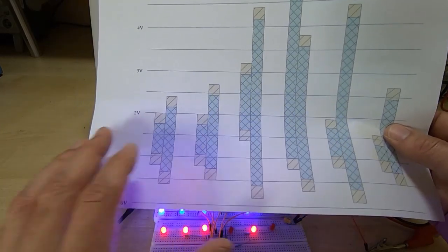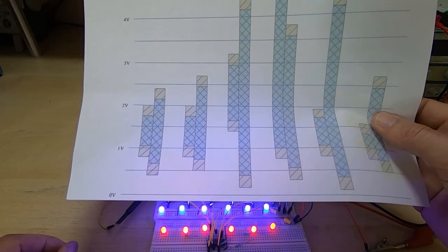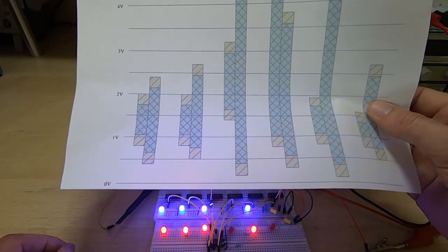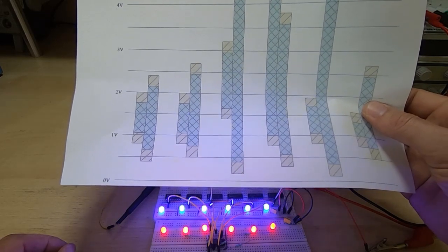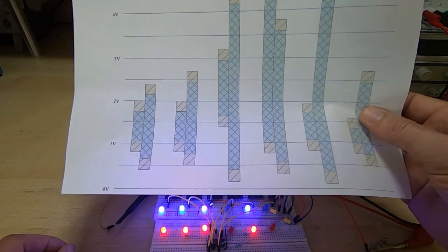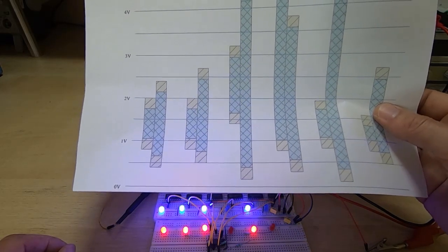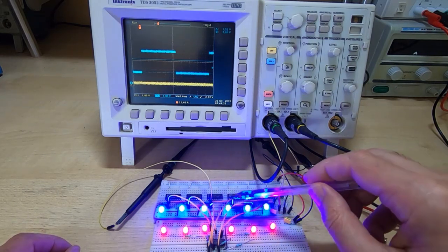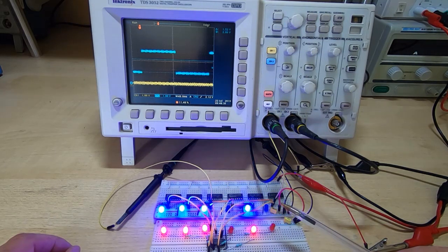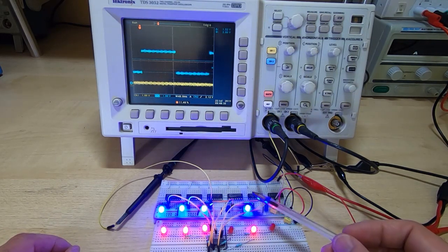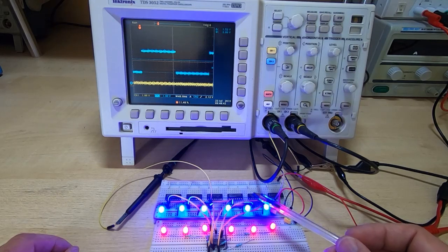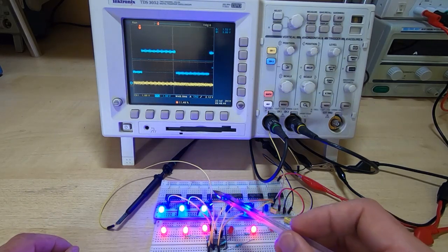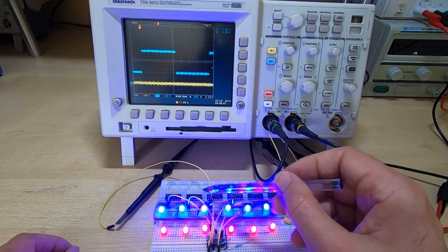Now there is a lot of ambiguity in this because it does vary slightly from manufacturer to manufacturer and chip type to chip type, and of course depending on the supply voltage and the fan out that's being used, you'll get different results. Now one thing that's causing this strange behavior is that the inputs are not isolated, and you have to bear in mind that the inputs to each of these devices have different circuitry, and that will in effect change the voltage levels going to the other devices.